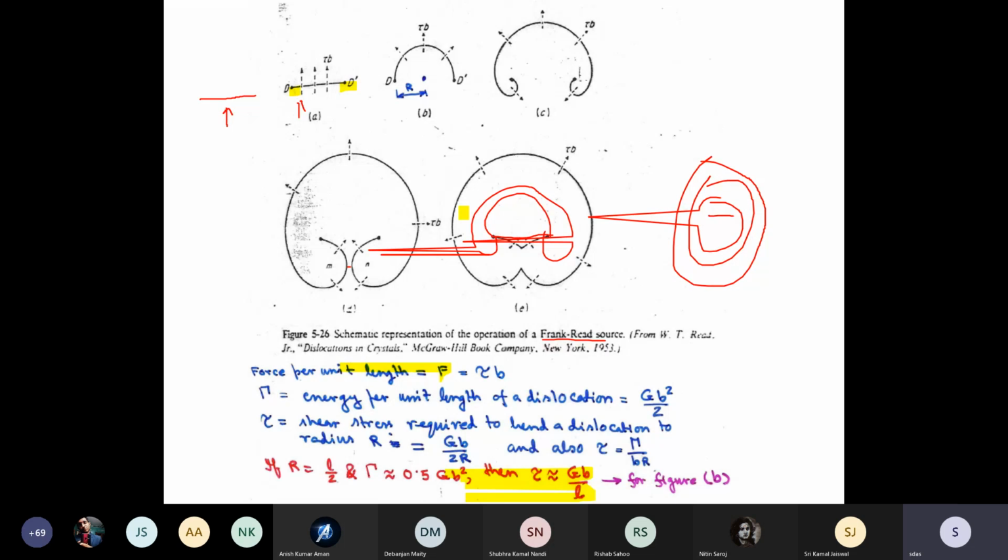So there are materials which are called precipitation hardenable. You increase the strength of that material by forming very fine precipitates uniformly distributed throughout the matrix. Turbine blades and jet engines are made out of nickel-based superalloys. They have a gamma prime precipitate for the same purpose. The aluminium pots and pans in your kitchen also have fine precipitates.